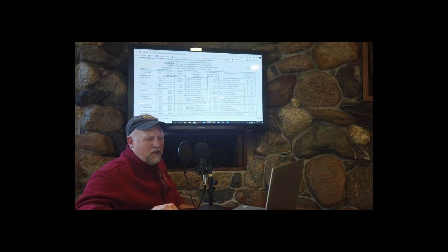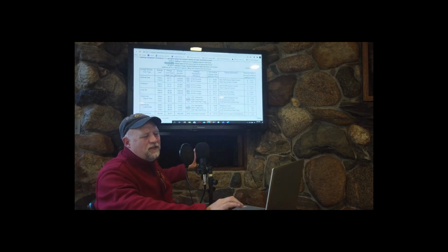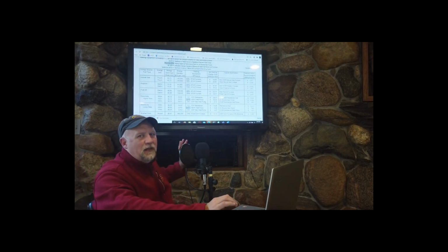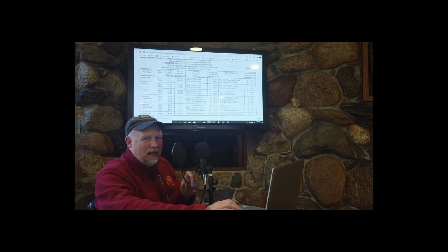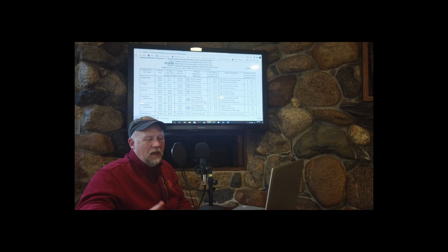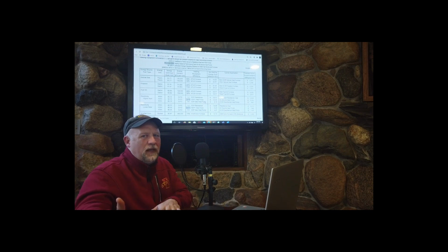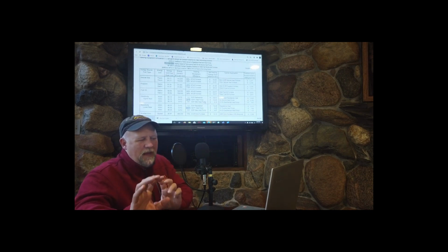And something to be cautious of here. This is not like saying this is 360% efficient. It's not generating electricity magically. But what it is doing, it is transferring more heat from the ground than it is consuming in electricity. And I hope everybody understands that particular concept.